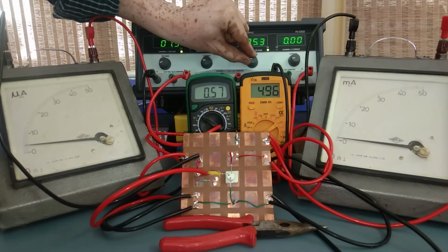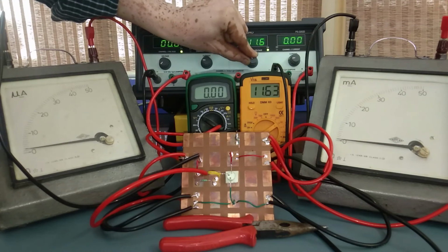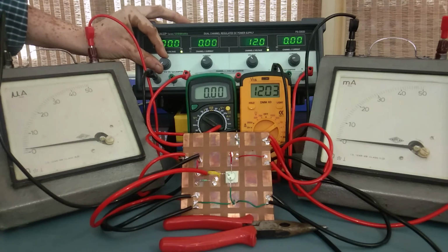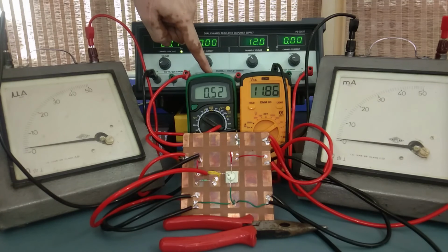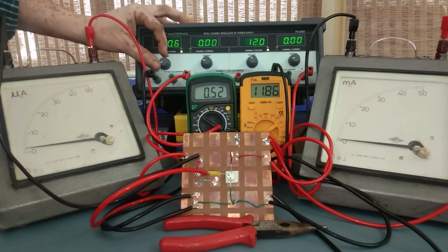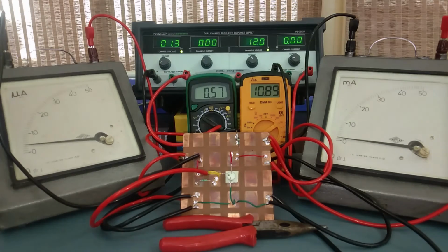Now we will go for some higher value. Maybe I will go for 12 volt. Now we will find that cut-in voltage will further increase. You can see here, even at 0.52 volt of VBE there is no base current, because now it has increased to a significant extent. Now you can find there is the deflection or the gradual increase in current that we can note.